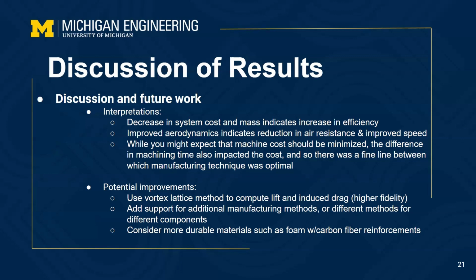Some potential improvements could be using a vortex lattice code, which is a higher fidelity aerodynamics code than what we use to compute the lift and drag. There are differential vortex lattice codes that exist, just not in MATLAB. And adding support for additional manufacturing methods or different methods for different components, or considering other materials such as foam with carbon reinforcements, which might be more durable and more cost-effective to produce at scale.